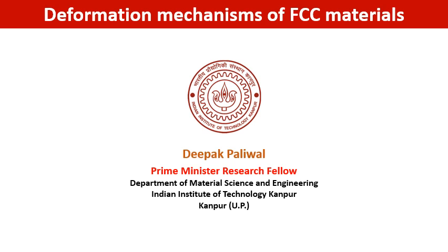In this video series, we will learn about the deformation mechanisms of the FCC materials. Before going to the actual deformation mechanisms of the FCC material, first we will try to understand the basics related to the FCC, BCC and simple cubic: what is the volume fraction of the unit cell, how the atoms are arranged inside the FCC, BCC, simple cubic, what are the close-packed planes, what are the close-packed directions, and what are the slip systems in case of BCC or FCC, so that we can have a good idea about all these things. After that we can jump into the deformation mechanisms of the FCC materials.